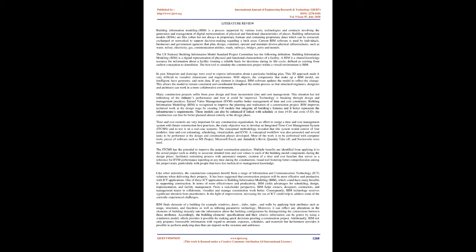We collected data such as the floor plans and elevations of the new Gandhi Block, School of Architecture, in VIT Vellore campus, and created a three-dimensional model of the building using the Revit 2018 software. By creating a 3D model, we were able to give a real-life representation of the building. We created the 3D model according to the dimensions and specifications in the floor plan and elevation provided to us. We then transferred the model to the Navisworks Manage software for simulating the time constraint.